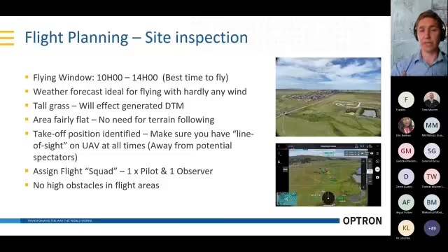We used various drones, but for this specific webinar, we're only going to focus on the Mavic 3 Enterprise datasets. As I've mentioned, we noticed tall grass that will ultimately affect the generated digital terrain model. The area is also fairly flat, so we didn't use the terrain following feature.